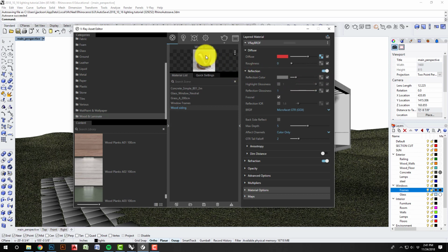Just like the window frames we made, it wouldn't be as crisp, so I'm going to drop this down to like 0.7. You can't make out anything, but we do get some variation. It will take on light a little bit, and we'll say that that's representing our finishing poly coat over the wood that gives it just a little bit of sheen.